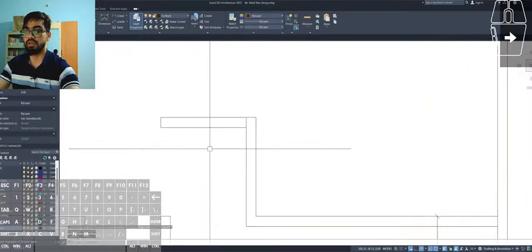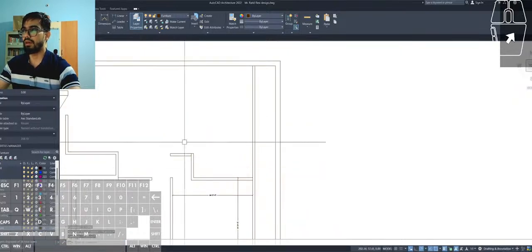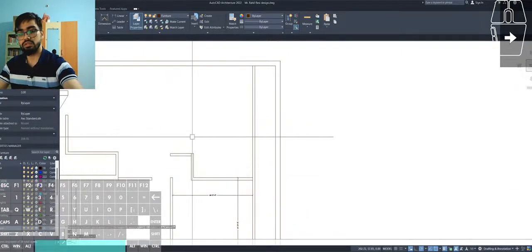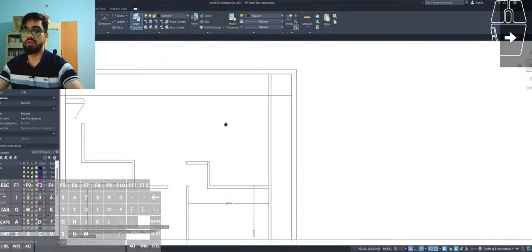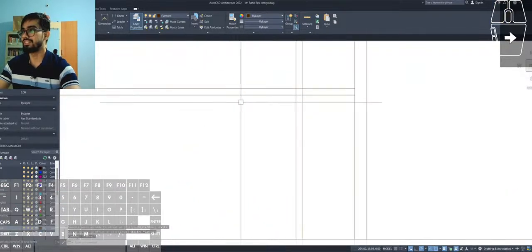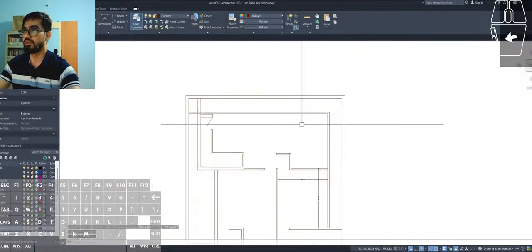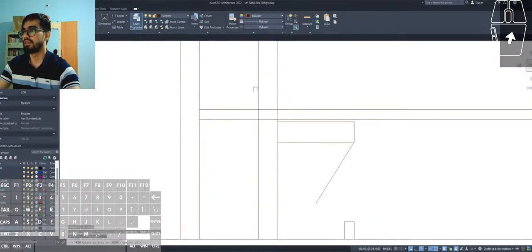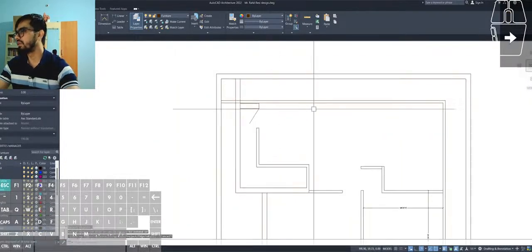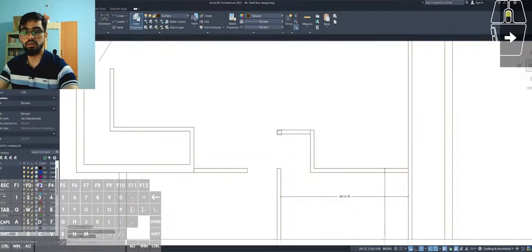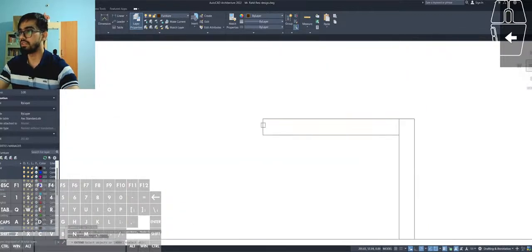We need that part, and then I'm going to have a balcony. So offset 1 meter, offset 0.115, because that's what the engineers like, instead of 0.15, which is the approximate. Wait. The balcony will be till here, so I'm gonna trim that later on. I'm going to extend this first.